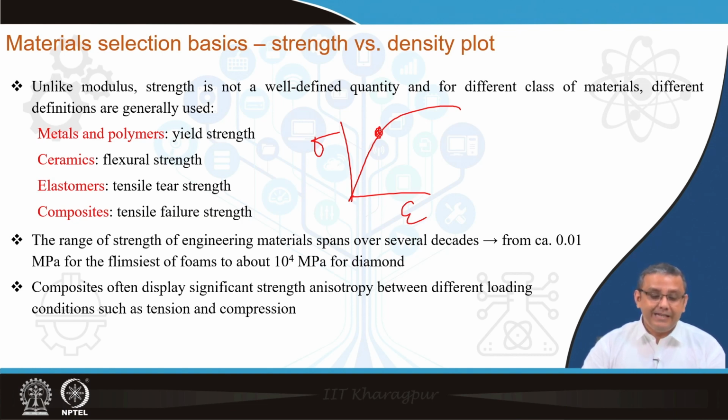In case of ceramics, it is pretty complicated, because ceramics are very weak in tension because of the extremely high brittleness, and ceramics are actually never tested under tensile loading. The compressive strength of ceramics is significantly higher, even in the range of 10 to 20 times higher than tensile strength, but it is more common to determine the strength of ceramics by a flexural test.